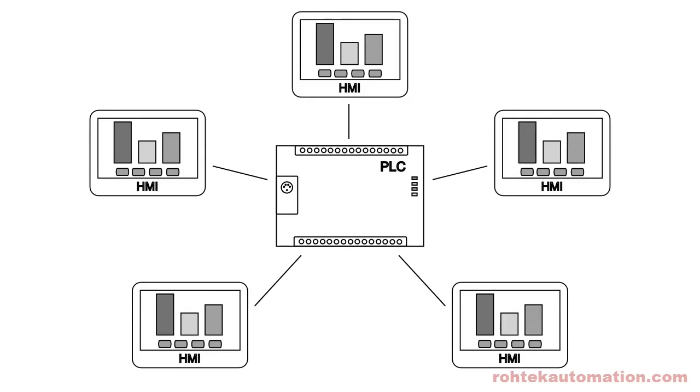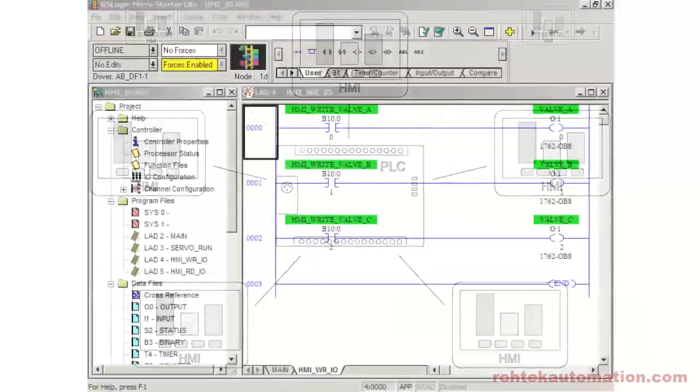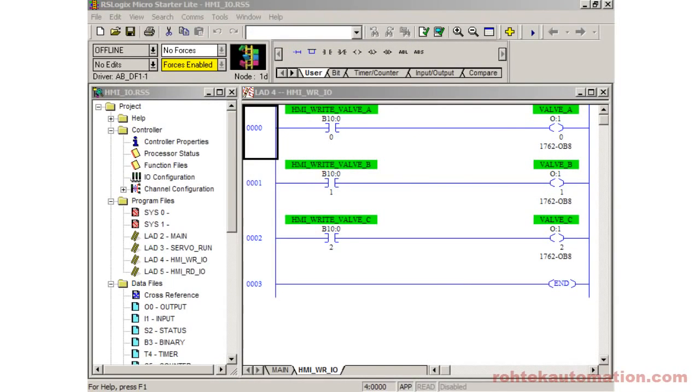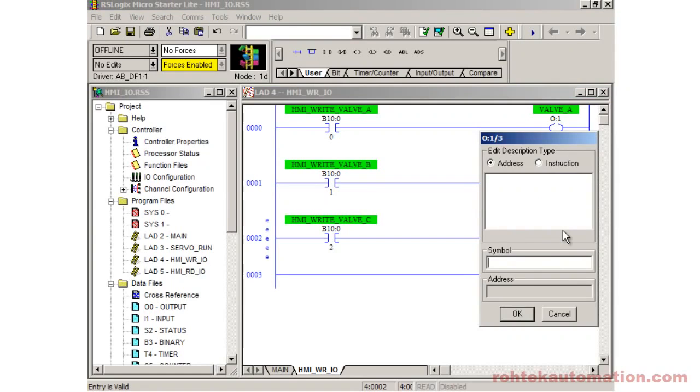And hopefully the person changing the PLC program will be aware of the affected HMIs, both local and remote. However, if we've implemented an HMI interface table in the PLC, there may need to be no change to the HMIs, only a remapping of the interface table in the PLC to the various PLC data areas affected.